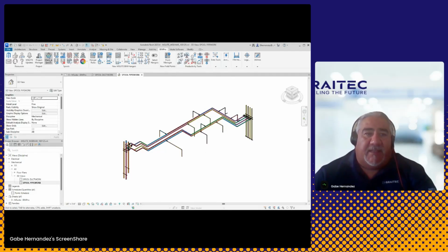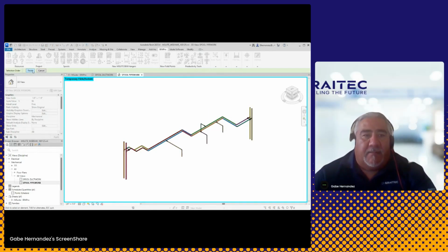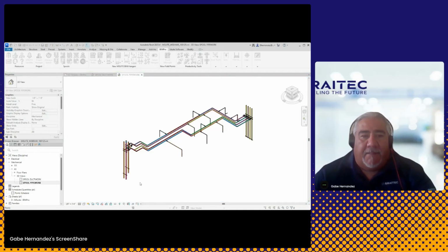So now that I got those done, again, I'll go back to my spool manager, and I'll pick on 1 through 23. All right, I'll add these to the chilled water supply package. Come on, supply. There we go. And then I'll fix the naming conventions as well. Put a dash in there, delete that out, finish it, and now I've been updated, right? And then I can go ahead and build all these, right? I just hit the build button.